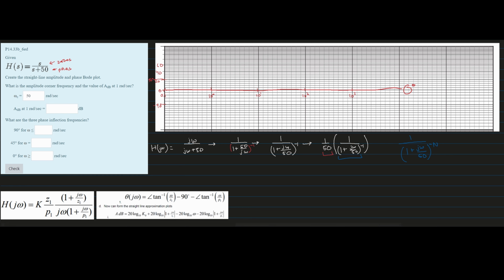And we can check where this goes. And we know this is going to go from p over 10 to p times 10. Our p is 50, so this is going from 5 to 500. So on our Bode diagram, we can mark out our 5. We can mark out our 500. And now we can chart this. So everything before 5 is 0 degrees slope. And then at 5, until we hit 500, we're going to have a 20 slope, and this is going to be in degrees.